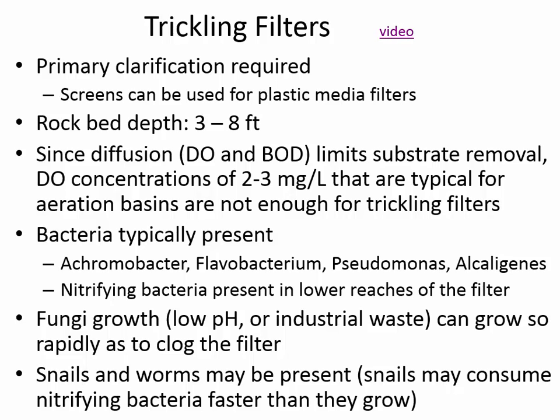The nitrifying bacteria set up at the bottom of the filter for the same reasons that they only selectively grow where they have a competitive advantage. At the top of the filter, the BOD concentration of the liquid is higher, and there are other microorganisms that outcompete the nitrifying bacteria. The nitrifying bacteria have slower kinetics, and so they grow where other bacteria don't want to. Not that they don't want to, but the other bacteria higher in the filter, closer to the source of the substrate, have a better advantage there.